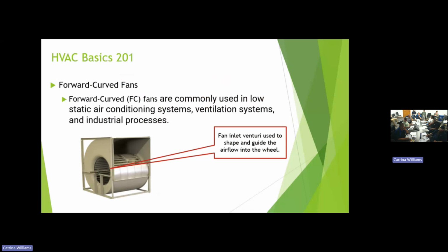Okay. And the negative thing of that, though, if you get in a dirty atmosphere, those blades load up with dust, dirt, whatever. And you have to go in there every once in a while and almost like a wire brush and scrape all that stuff off to get your performance back again. The toothbrush. So, but yes, as we said, they're cupped and they just scoop the air and push it out.